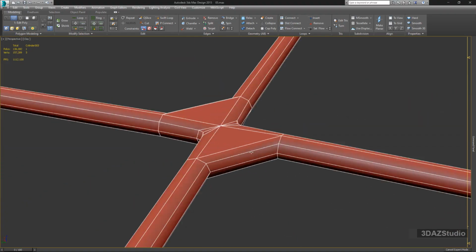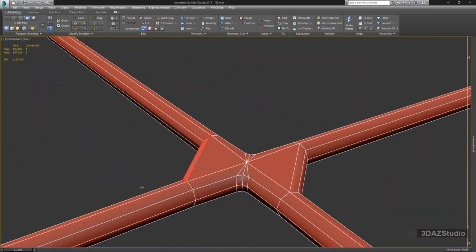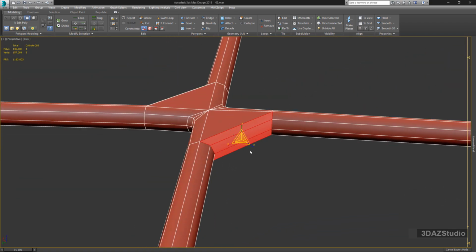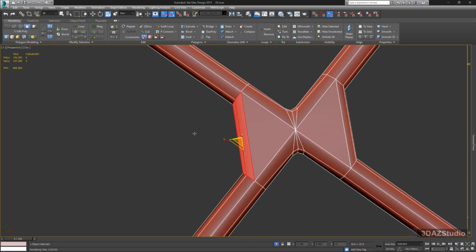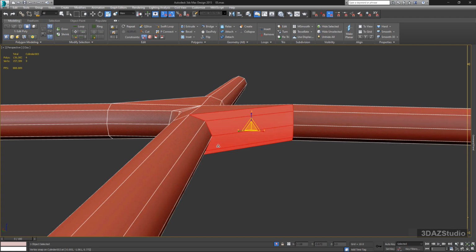Let's explore an alternative scenario, creating flat sides on the cap. Select the cap side polygons and use either the Scale tool or the Make Planar command. Notice how the cylinder deforms as a result of flattening the connected polygons. This behavior persists even when using local coordinates.